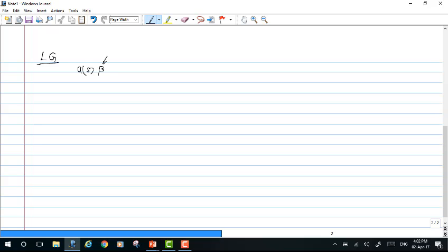So this entire loop gain, since it is a product of open loop gain with the feedback factor, let us try to see how it reacts at different frequencies. Let me try to map them. At omega equals 0, which means we apply a DC potential, and let us still assume that this open loop system has a single pole, I can write A of S as A naught divided by 1 plus S by omega P1, right?